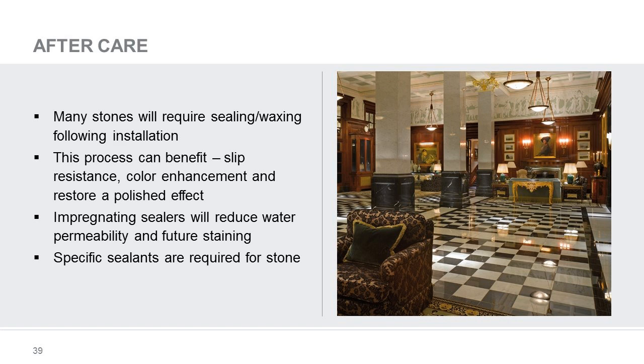Aftercare. Many stones will require sealing or waxing following an installation. This process can benefit slip resistance, color enhancement, and restore a polished effect. Impregnating sealers will reduce water permeability and future staining. Specific sealants are required for stone.